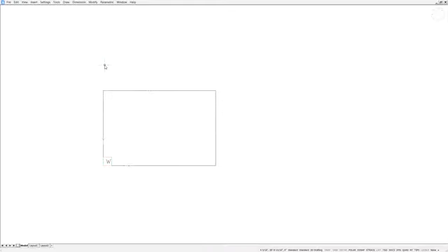We can do a whole session just on the quad, but I just want to emphasize this is super powerful, and you can literally do everything you need to do in BricsCAD without even using the command line or without displaying it. Because again, I could just type C here without the command line up, and you'll see it's displaying. Let me type it. I can start my circle. It's displaying the options, even though it's not taking up any space. So quad, super powerful. In the future, I will try to do a session just on the quad. But for right now, I want to go ahead and move on to a few other topics.